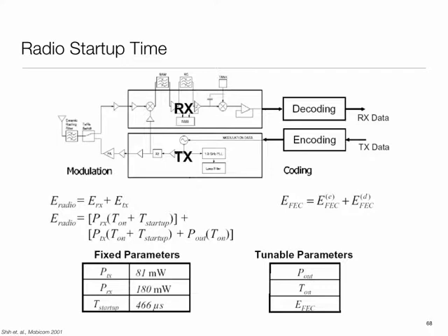This is equivalent to saying that if I am designing a processor which has to do sporadic activity, once in a while it has to wake up, process sensor data and do something, I better make sure that the wake up cost is kept as small as possible. The OS should not take 10 seconds to reboot for me to do a millisecond of work, because then I'm going to pay that 10 seconds all the time.